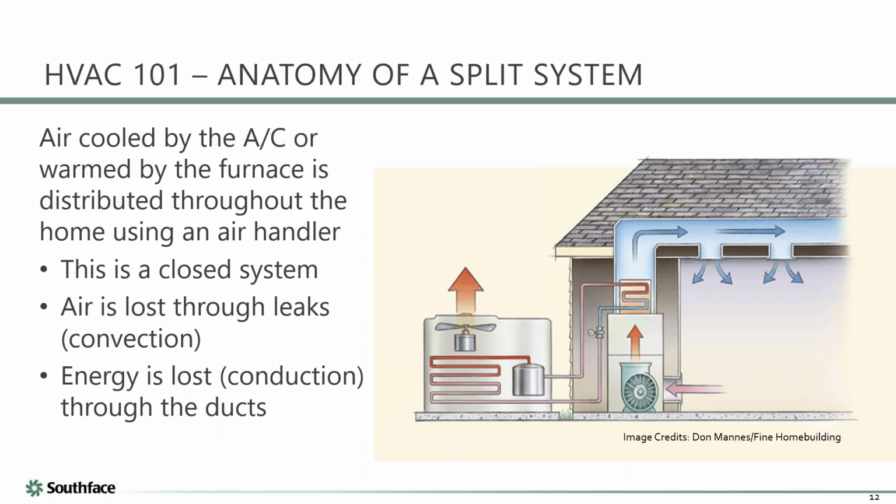What is happening in an HVAC system, in air conditioning mode, is we're pulling hot air from the house and blowing it across a cold refrigerant coil. So we're giving up heat from the air of the house, and then that air is leaving at a cooler, drier temperature and being put back into the house. And of course, we're catching condensate, liquid water, off the side of this and draining it away.